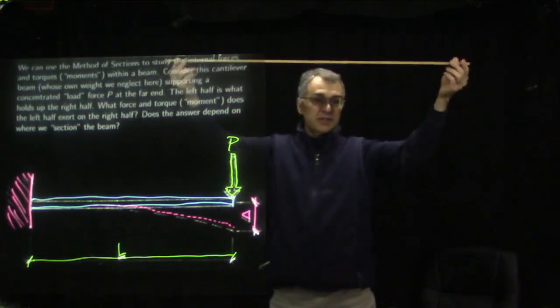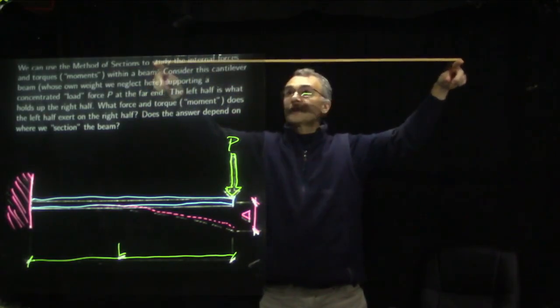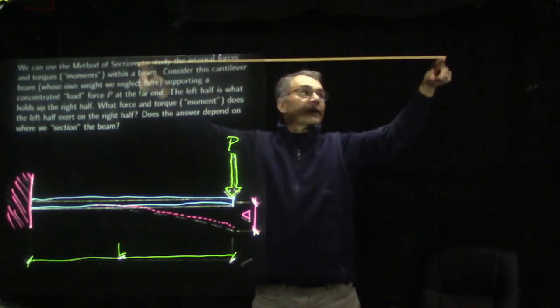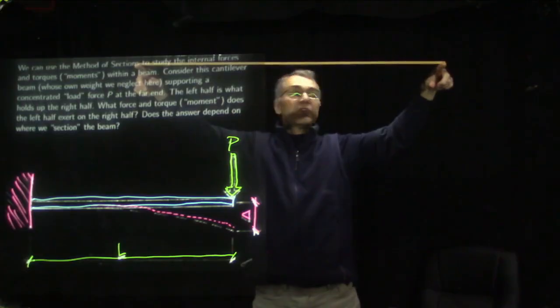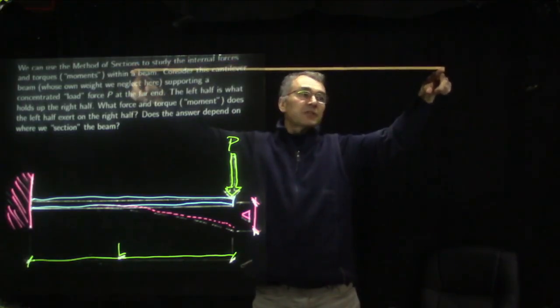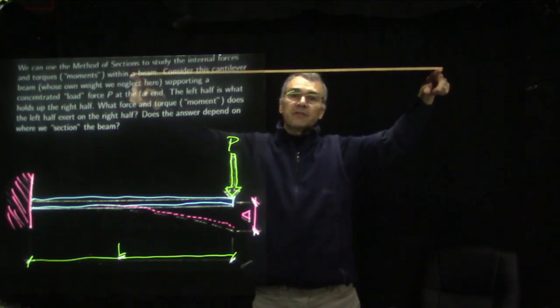And then the other most common case is a so-called simply supported beam, where you just have a single support under each far end. And by convention, so that you get three unknowns to solve for using statics, you have a hinge support on one side and a roller support on the other. Although in most cases, all the loads are vertical, so it's really just one vertical force on one side and one vertical force on the other side in the most common case.